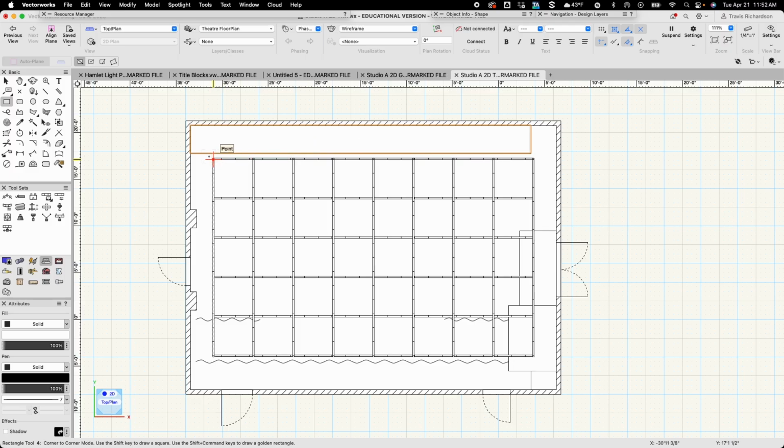Then I'm going to start another one at the bottom left smart point of the rectangle that I just drew. There's a section over here. So this one I'm going to tab in and make it 3 feet on the X and -6 feet on the Y. That's going to nudge it right up against that little concrete bump out that we drafted initially, which is just perfect. I'll click to complete that, and there's my second riser.